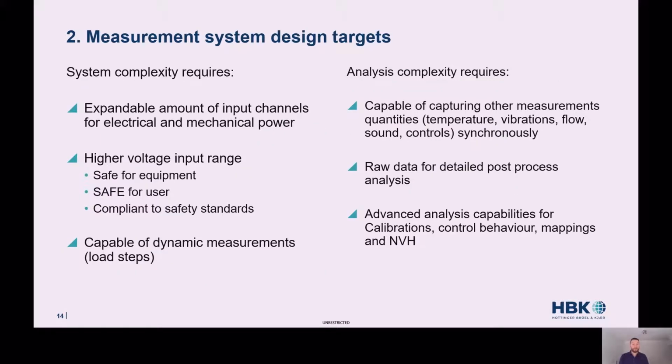So let's go back to our measurement system design targets and add in the analysis complexity as well. For the system complexity, we require an expandable amount of input channels for both electrical and mechanical power, higher voltage input ranges, which should be safe for the equipment, for the user, as well as compliant to safety standards, and should be capable of dynamic measurements to acquire any load steps of machines clutching in and out.